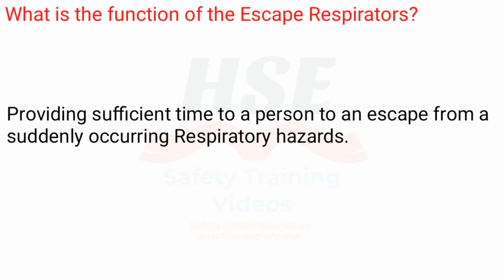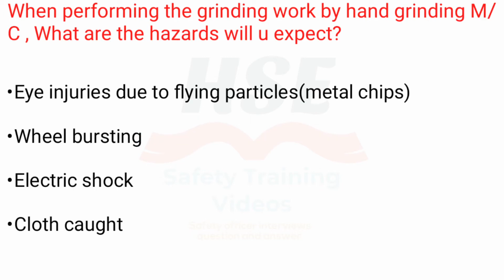What is the function of the escape respirators? Providing sufficient time to a person to escape from a suddenly occurring respiratory hazard. When performing grinding work by hand grinding machine, what hazards will you expect? Eye injuries due to flying particles, metal chips, wheel bursting, electric shock, cloth caught.